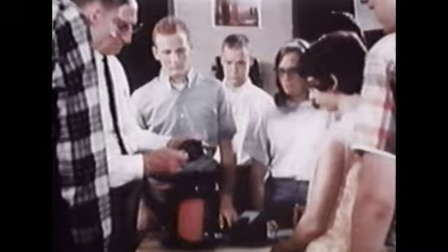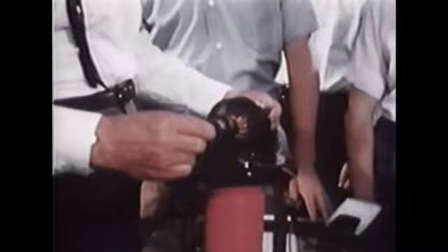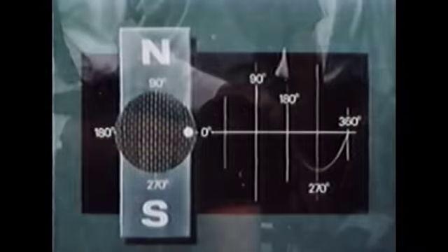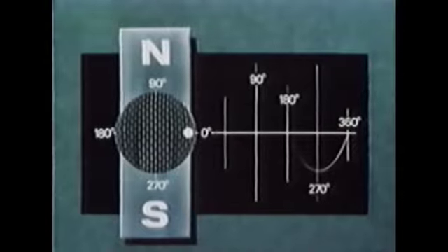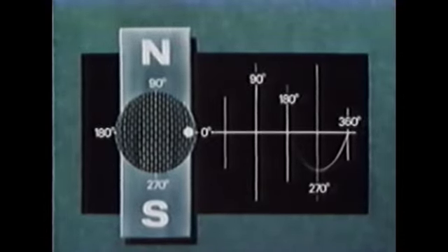In a generator, the space through which the coil or rotor must be moved to produce 1 cycle depends on the number of magnetic poles in the generator. In a 2-pole generator, for example, it must make 1 complete revolution. Therefore, 360 mechanical degrees is equivalent to 360 electrical degrees, or 1 cycle. In a 4-pole generator, however, the coil need only move through 180 mechanical degrees for 1 complete cycle, or 360 electrical degrees. Each complete mechanical revolution then produces 2 cycles.